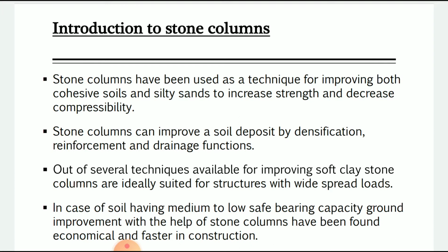My first point is about the introduction of the stone column. When we talk about the stone column, you know that it is a technique which improves both types of soil, that is cohesive as well as silty sands, to increase the strength and to decrease the compressibility of the soil. Second, the stone column can improve the soil deposit by densification, reinforcement and drainage functions.